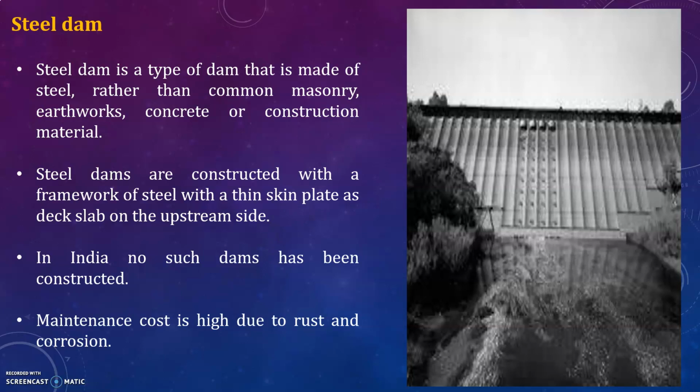This arrangement introduces a tensile force in the deck girders, which is resisted either by anchoring the deck girder into the foundation at the upstream toe or by framing the entire bent rigidly together so that the moment of the weight of the water on the lower part of the deck may be utilized to offset the moment of the cantilever.